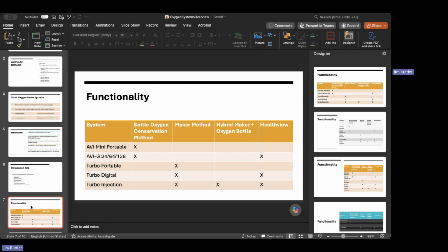We got everything approved through NORSEE, non-required safety enhancing equipment. So it's approved for installation in all Part 23 aircraft, but there is a limitation on what that approval covers, which means you can't use it where oxygen is legally required. All the systems include a standalone oxygen bottle to keep you legal. You should use that above the altitudes where you're legally required to use oxygen. For experimental aircraft, there is no limit. It's the same equipment and continues to work above those altitudes.